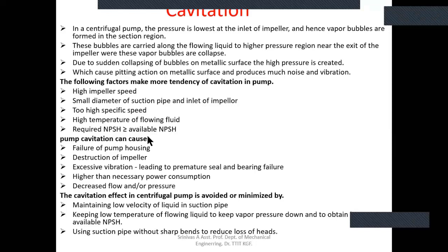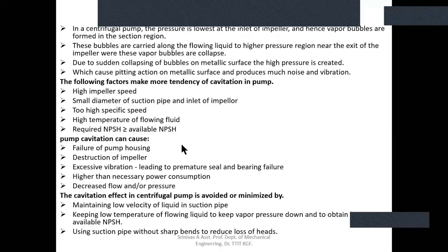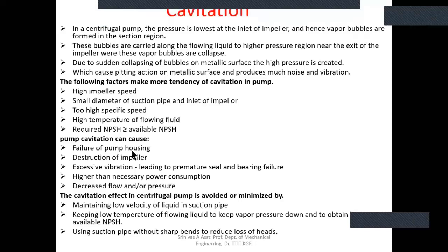And in the pump, if cavitation occurs, what damage does it do? The failure of the pump housing, that is the outer casing, will fail, or the impeller gets damaged because of the bubbles expanding or opening at the blades, and excessive vibration because of the bubbles and movements.